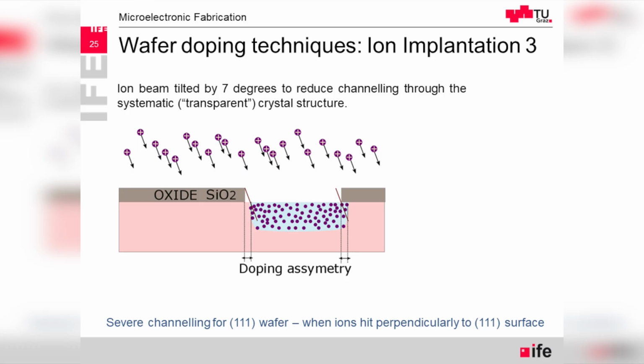And what is particularly dangerous in ion implantation: if you would have a 3D model of a larger silicon structure, you can find those as apps online, and you rotate it, you can find certain orientations where you can just see through. There is an opening between all the ions, and it's a repetitive pattern, so it goes to the other side of the wafer. Maybe not that bad, but ions can have this so-called channeling.